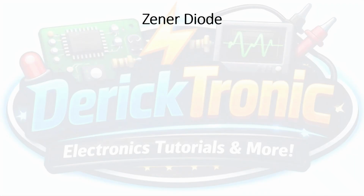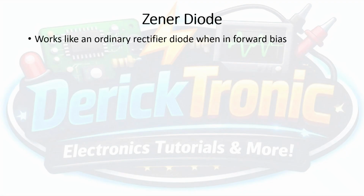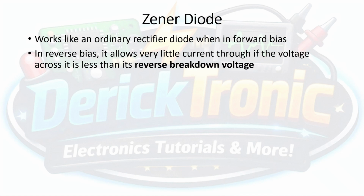Today, we will be building a voltage regulator circuit that contains a component known as a Zener diode. Let us first compare the Zener diode with the rectifier diodes we saw in our previous video. When connected in forward bias, the Zener diode will operate similar to a rectifier diode. In reverse bias, similar to the rectifier diode, it will allow very little current to flow through it for as long as the voltage across the Zener diode is less than its reverse breakdown voltage. We will take a closer look at what that reverse breakdown voltage is later on.